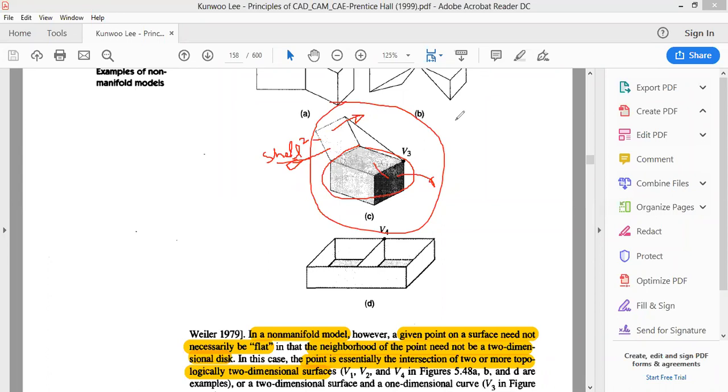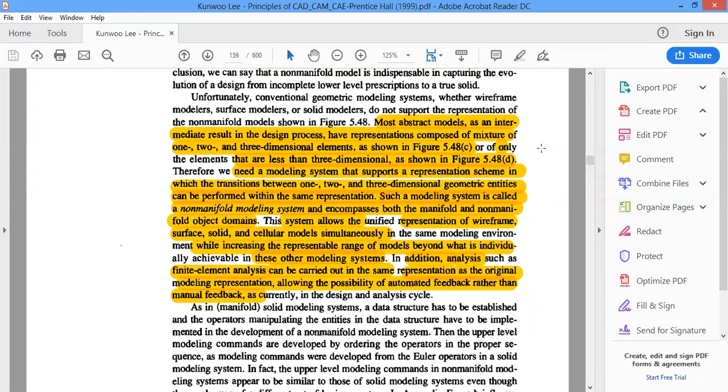So in the same model, many different types of mesh elements have to be chosen. One way of identifying this is based upon the type of model, whether it's going to be a solid model or the other portions are going to be made up of thin sections. So according to the varieties, the mesh elements have to be chosen, right?